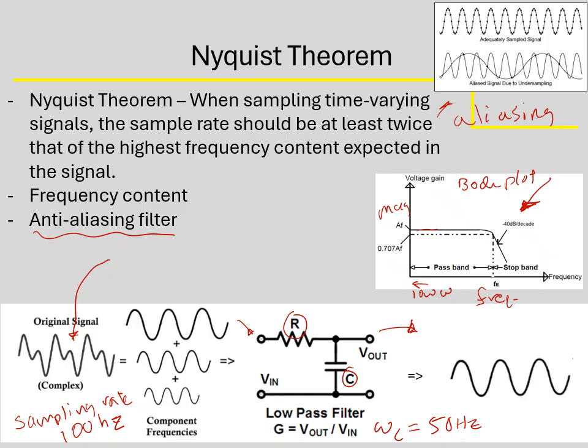As frequencies get high, the signals get attenuated, they get reduced. This is actually a second order low pass filter. I can tell because of this 40 decibels per decade. Now I'm giving you flashbacks for those of you who have taken Mech 325. So that makes it a second order.